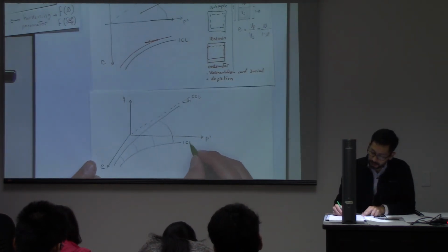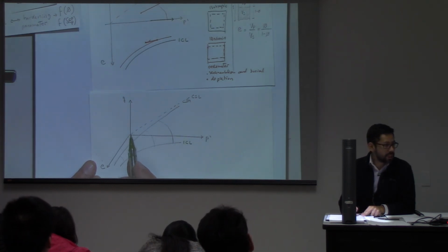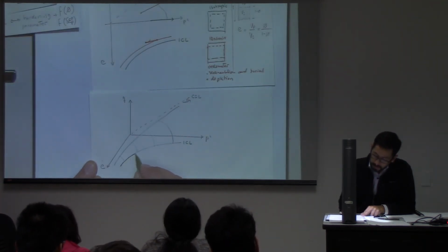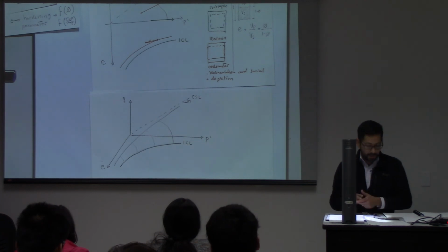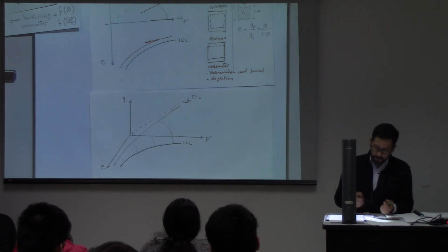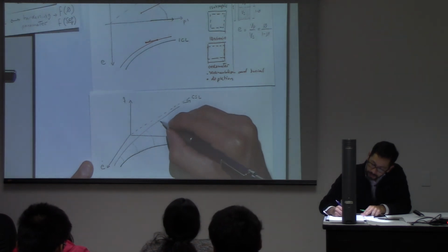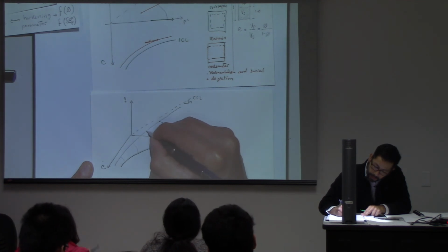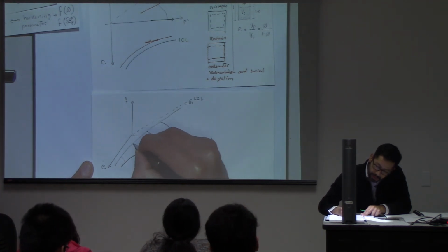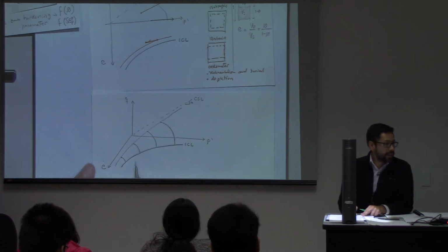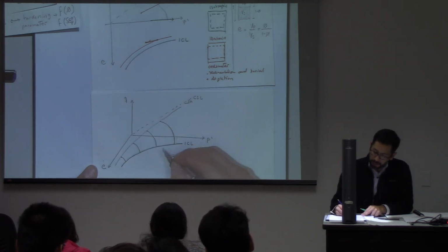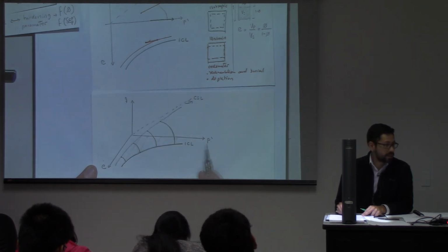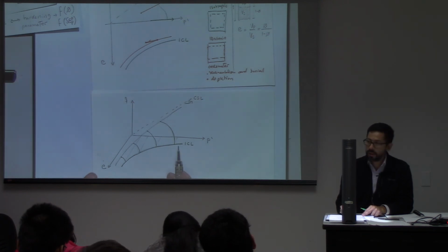So this is the isotropic consolidation line. When Q is equal to 0, that line is this line over here. And these over here are your yield surfaces, the half of the ellipse. And what this extended yield surface now in 3 dimensions shows is that the value of P naught, which will be the projection of this point onto this axis, is a function of porosity.